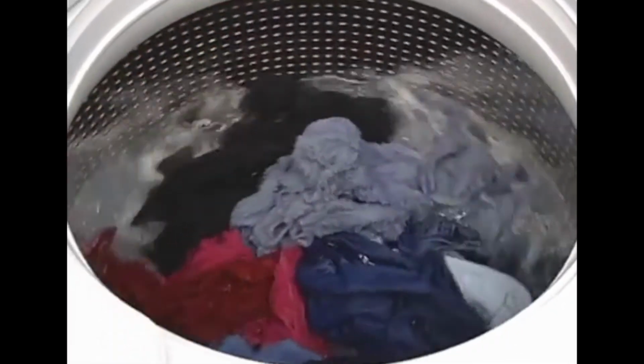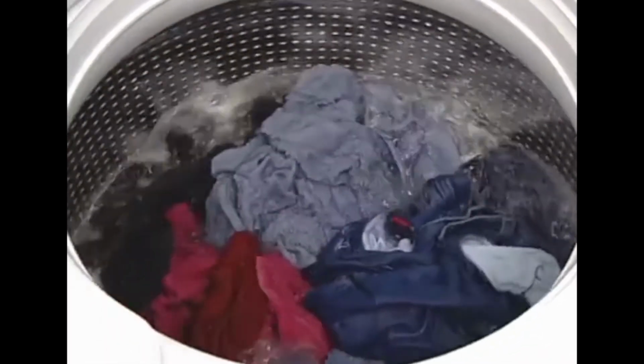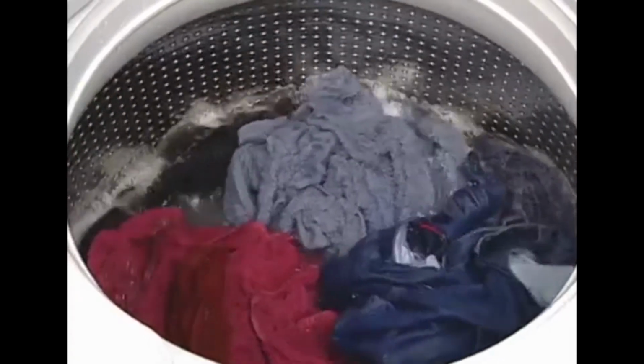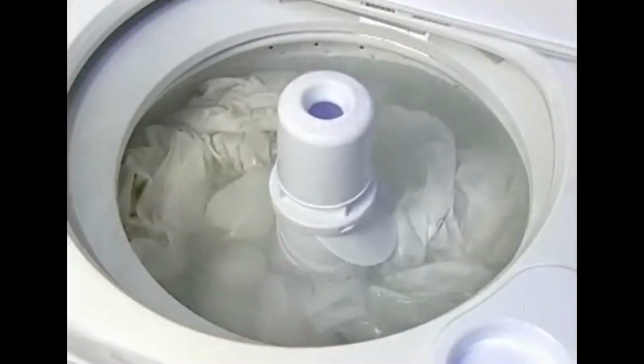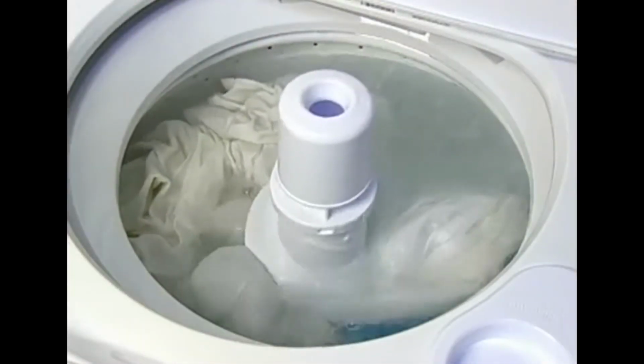Level on the floor. It's abnormal for a washing machine to vibrate the floor and walls of the laundry room. If the washing machine is not exactly leveled, with all 4 legs on the floor, it may rock back and forth and vibrate strongly. It's best to keep the machine as close to the floor as possible. The closer the machine sits to the floor, the less it will vibrate.